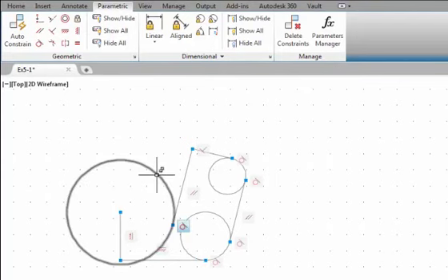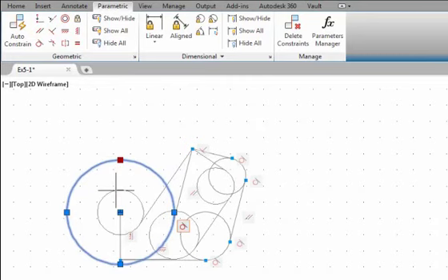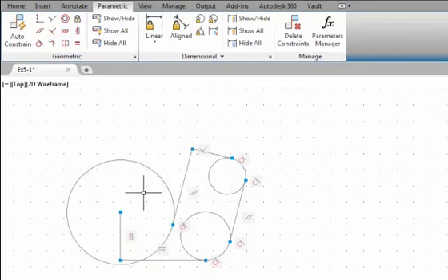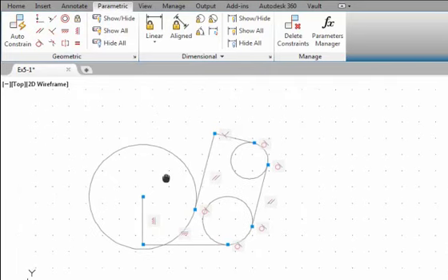Notice that I can use the grid point editing approach on any of the objects I've created so far, and no matter how I adjust, the established geometric constraints are always maintained. The parametric sketching approach allows us to experiment with adjusting the design. For example, during the initial conceptual design stage, a lot of the time we really don't have anything finalized, and the parametric sketching tools would allow us to do some experimenting.